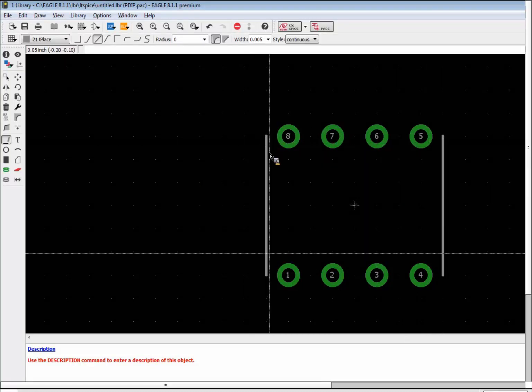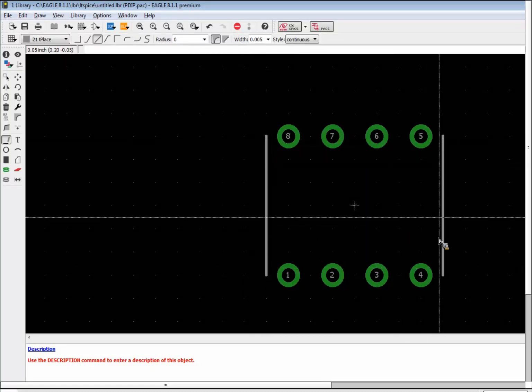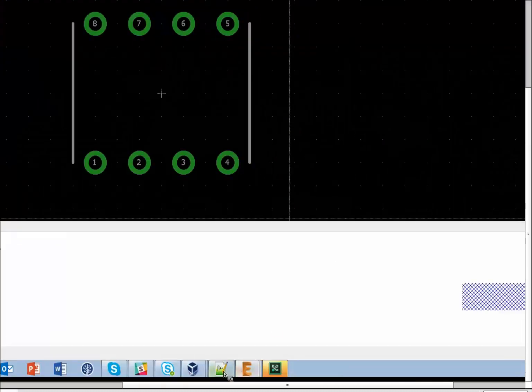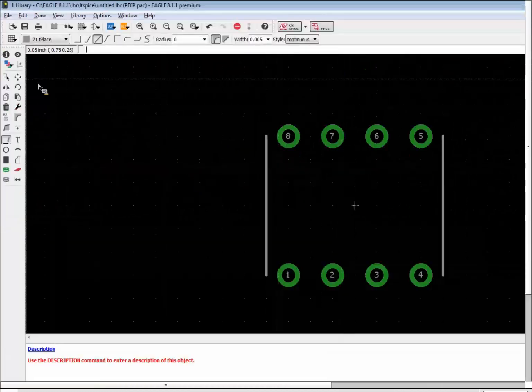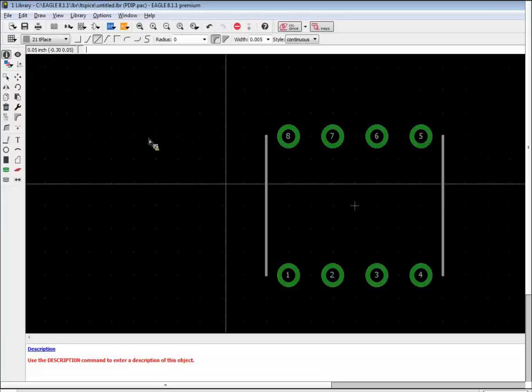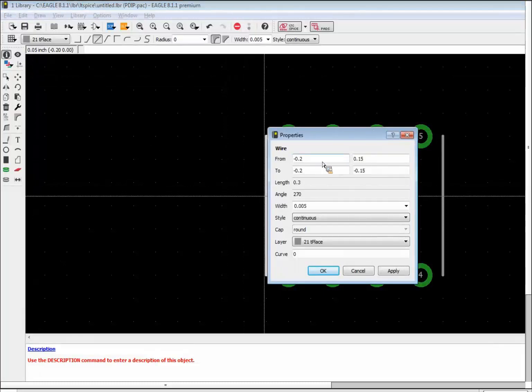Now here, I've exceeded a little bit that width specification that we have, right? Because we had 0.26. Now what could I do to fix that? There's a lot of ways to skin this cat, but the easiest one is to go Info, and we can just change the points here. So if we want to get 0.26, then half of 0.26 would be 0.13.